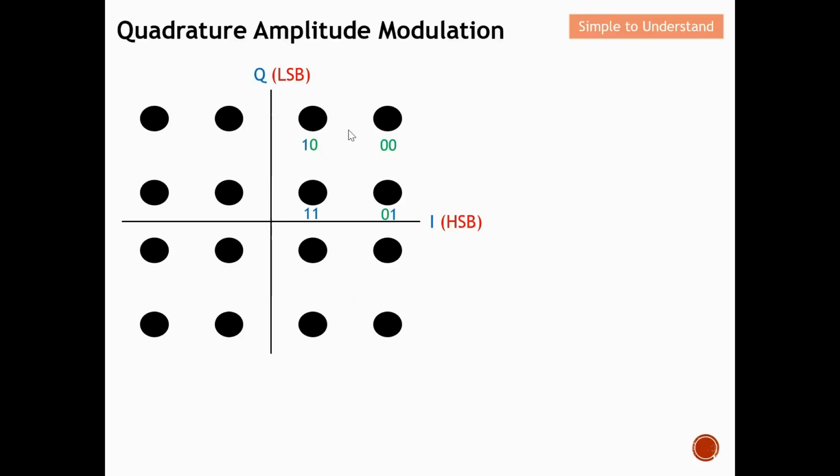So next, once I have done this, I will do a mirror image. This will be a mirror image, and this will be a mirror image. So I have done these two zones of 4 QAM. Next, again, another mirror image on the other side here. So I will be doing another mirror image. Basically, you can see from here, these are all mirror images. So I have done the so-called LSB bits of all the 16 points over here. I have the lowest 2 bits done.